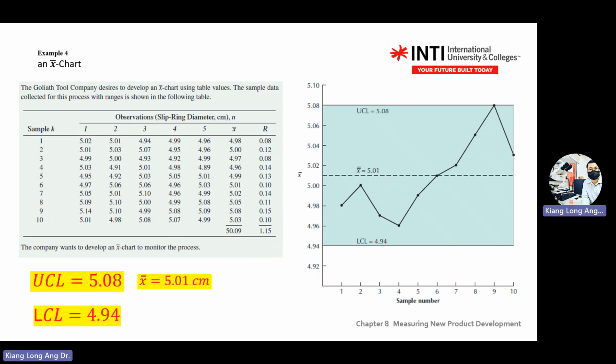When the machine cuts, maybe the blade is not sharp enough, so the dimension keeps becoming bigger and bigger. But when it comes to compression, when you assemble things, there is a compression machine. You want to hit the things and join together. So when you reach that station, suddenly everything fits into the specification. When it comes to station number 10, it suddenly bounced back.